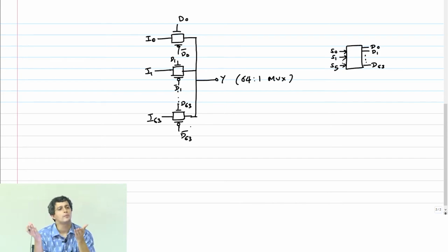Okay, how do you implement a decoder? Well, that again cannot be done just like that. For example, if I want a 6 input NAND gate, AND gate, I cannot do it, right? Because of logical effort reasons. Therefore, you build this from smaller 3:8 decoders. You build 3:8 decoders, then cascade them, and then build your 6:64 decoder, right?